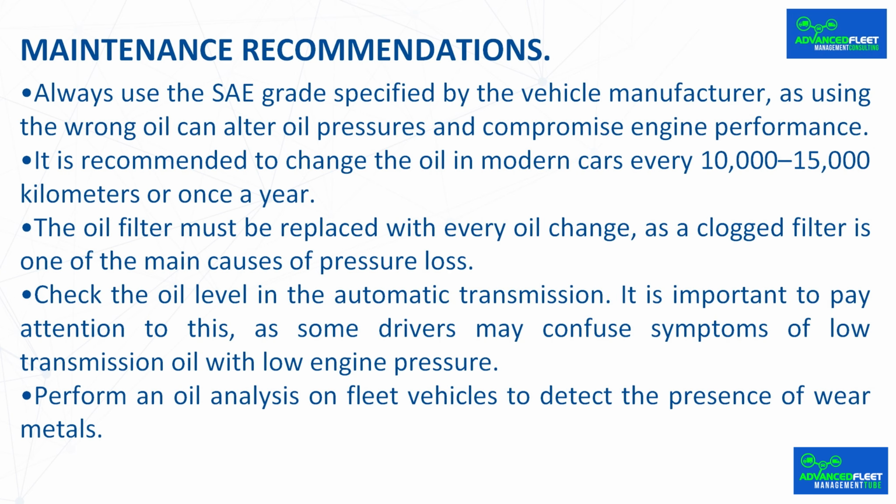Always use the SAE grade specified by the vehicle manufacturer, as using the wrong oil can alter oil pressures and compromise engine performance. It is recommended to change the oil in modern cars every 10,000 to 15,000 kilometers or once a year. The oil filter must be replaced with every oil change, as a clogged filter is one of the main causes of pressure loss.